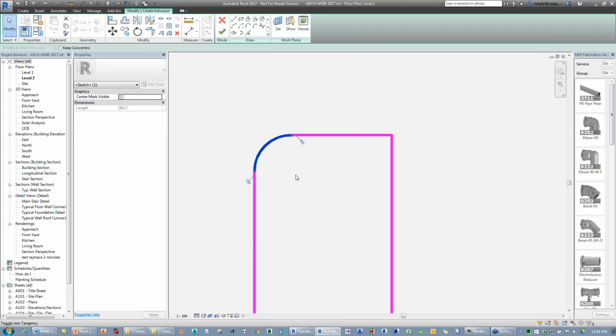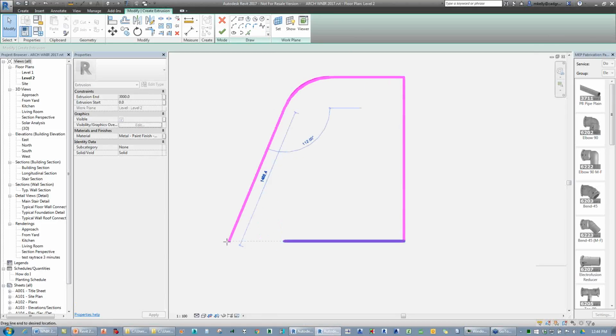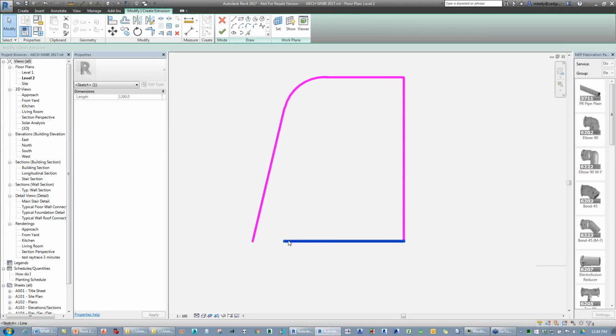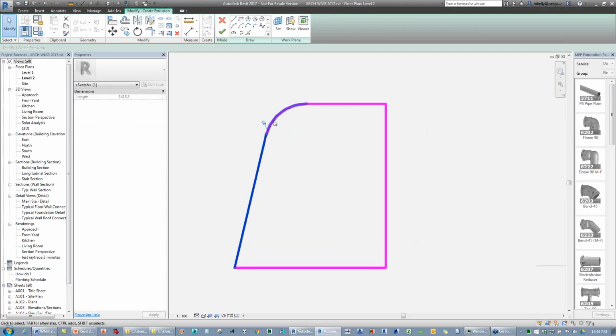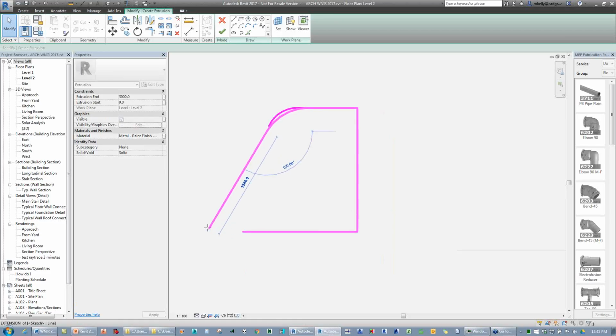You can see here I've now got these tangential locks. Revit now creates that relationship and locks that. I have played around with this a little bit, and in terms of making this parametric, I'm not quite sure. I think you might have to put a conditional statement in there that stops it from going beyond a certain angle, because you can see that it will break, maybe not.